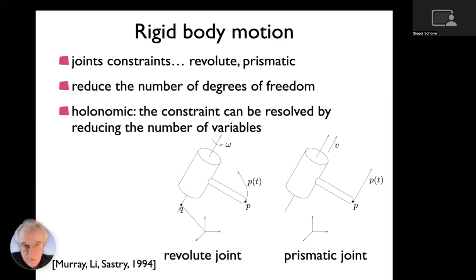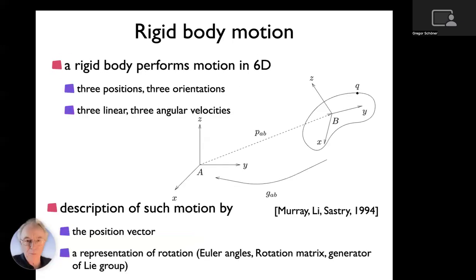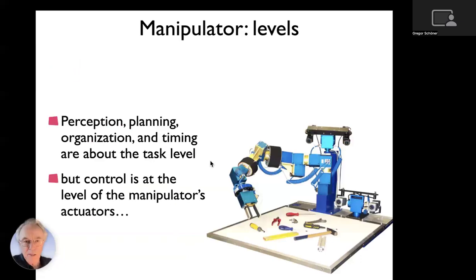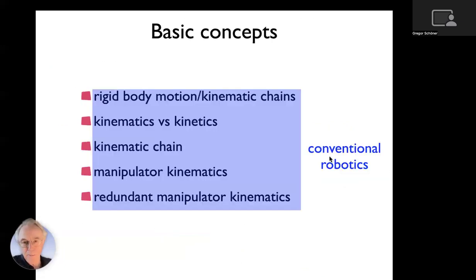And that is not common in robots. So commonly robots do that by chaining 3 revolute joints with different orientations to emulate that. And the robot arm that I flashed previously, like this one here, has a shoulder that is a sequence of 3 revolute joints that then make up this spherical joint.